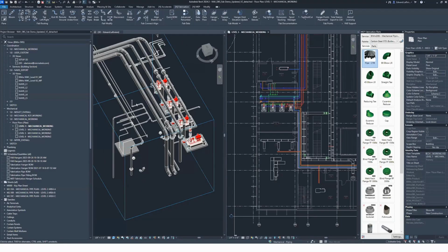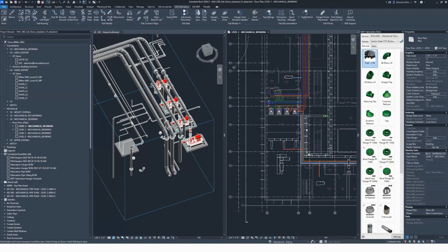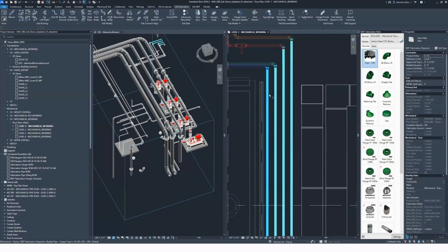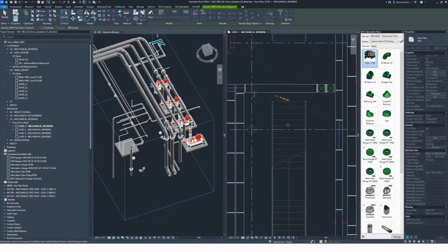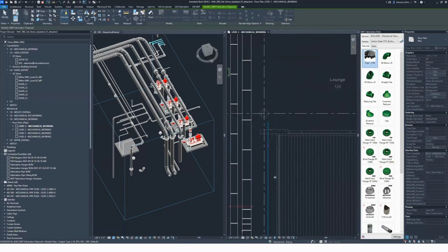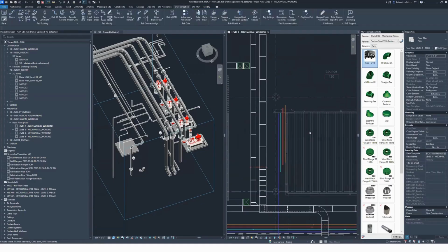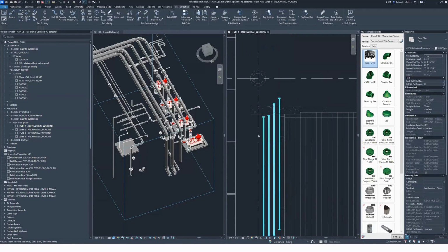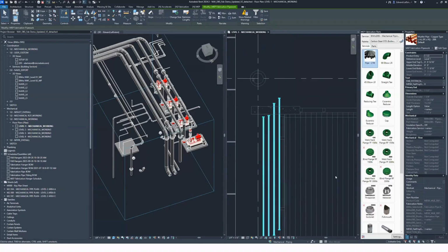So I mentioned some hidden functionality. I've got one other quick piece of hidden functionality for you, and I think we should probably take a look at duct, so we've got time to get through everything else. Now those elbow tools, they actually support pre-selection. Now I've got a single height rack over here. You could have a multi-tier, it doesn't matter to us. Just make sure you've already spaced your elements out.